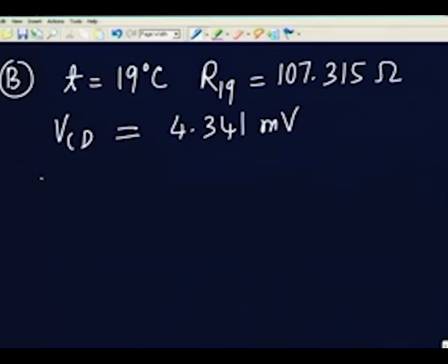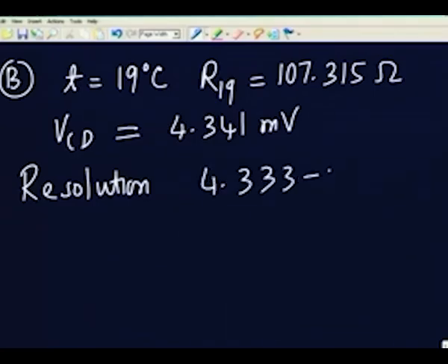And if you go back and check the resolution required, 4.333 and 4.341, that will be 4.333 minus 4.341, which is about 8 millivolts.